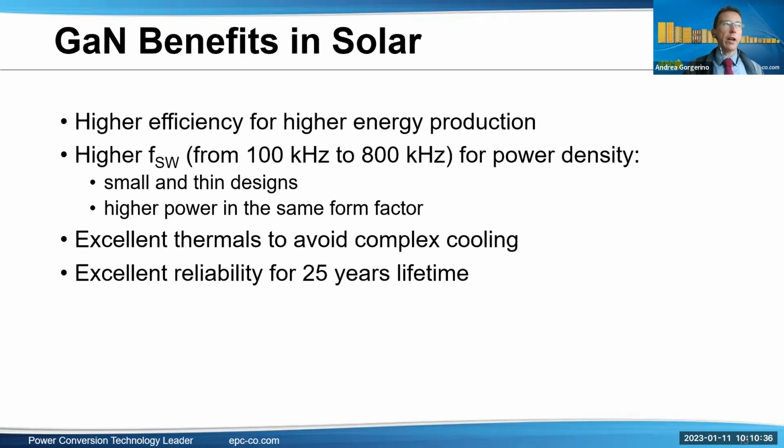Typically, silicon FET systems are running at 100 kilohertz maybe, and we can definitely go to 800 kilohertz, maybe even higher. And this is for power density. This can be used in several ways. It can lead to small and thin designs, or it can lead to higher power in the same form factor,